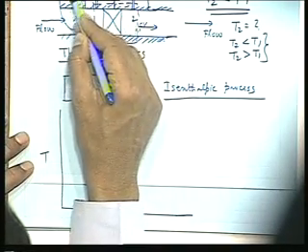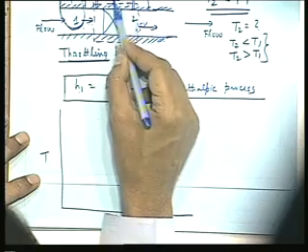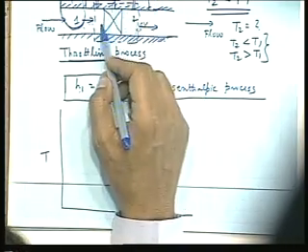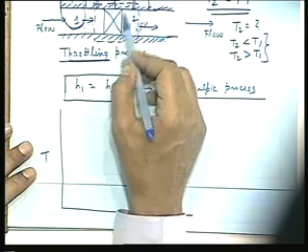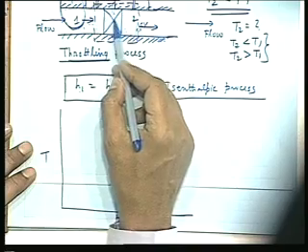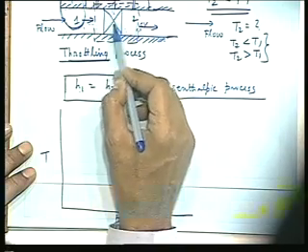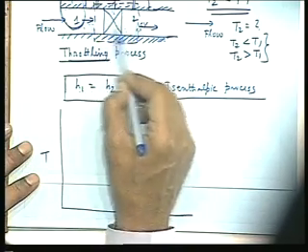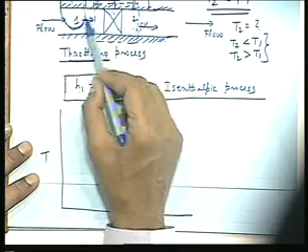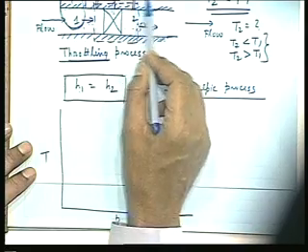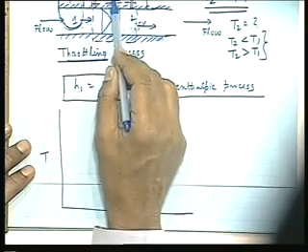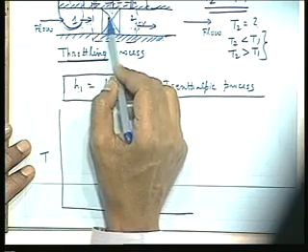If I keep this P1, T1 fixed, but I go on varying the position of the valve, that means if I throttle to different pressures and temperatures, starting from the fully closed position and slowly opening the valve, then different valve settings create different restricted passage areas. Which means that if I throttle to different pressure and temperature, you will see that the throttling pressure and temperature will be different. For the same initial condition, if I throttle at different valve settings,